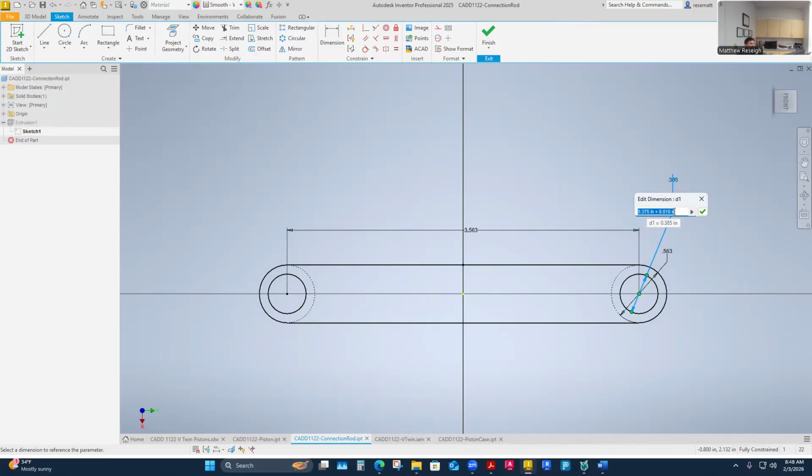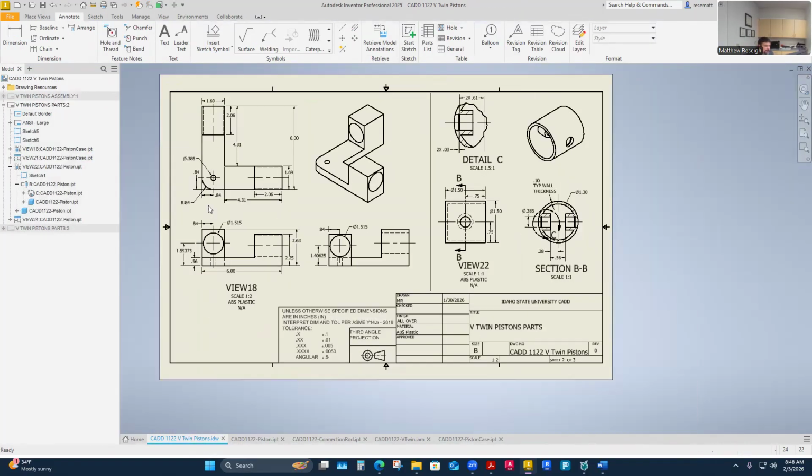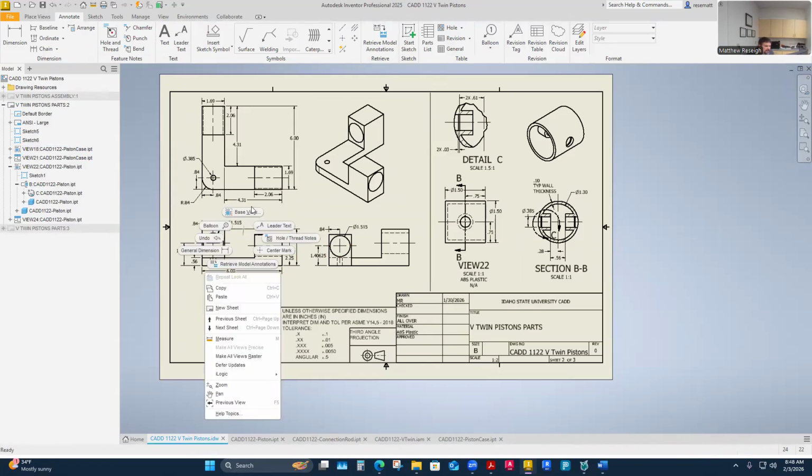Yep, my hole's through there. Same hole. Yes, every hole that I needed the shaft to fit through, I toleranced to 10 thousandths over the shaft size. Except the one that you missed just briefly, which was the piston case. Open. Sorry, I'm in my.